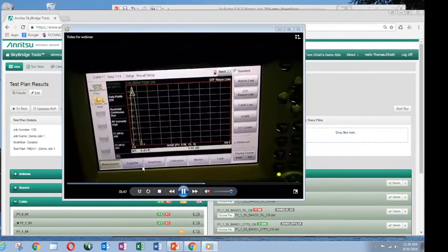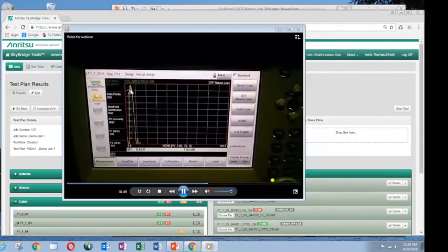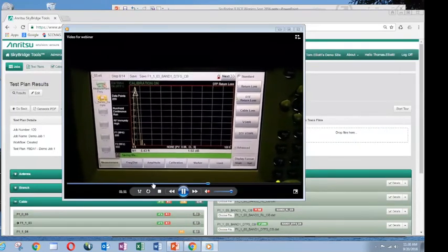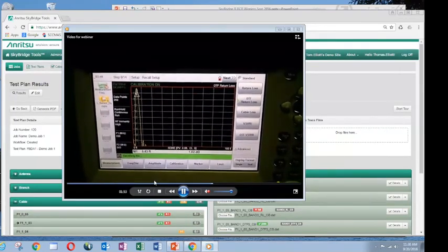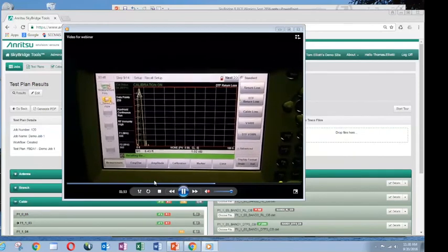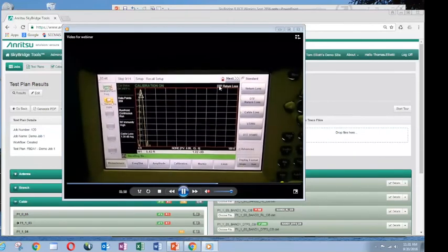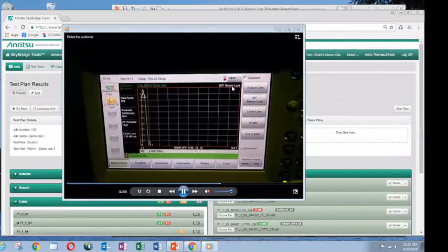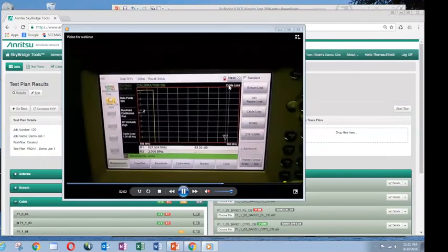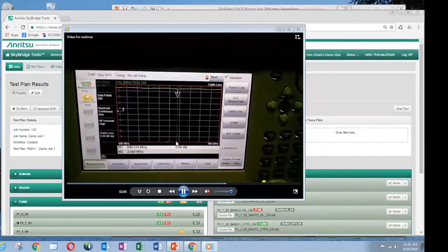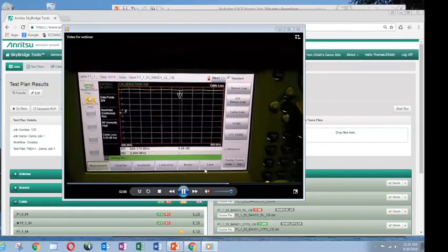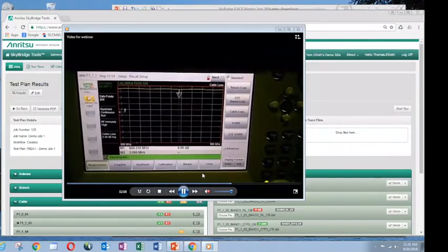And now I'm going to distance default, and I have a marker to the max. That was part of the script. We're saving that file to the memory stick. Okay. Recalling the next file, that was the DTF return loss. Now we're going to a cable loss, and we're going to 698 to 960 again. As soon as that sweeps, we'll push the next button.